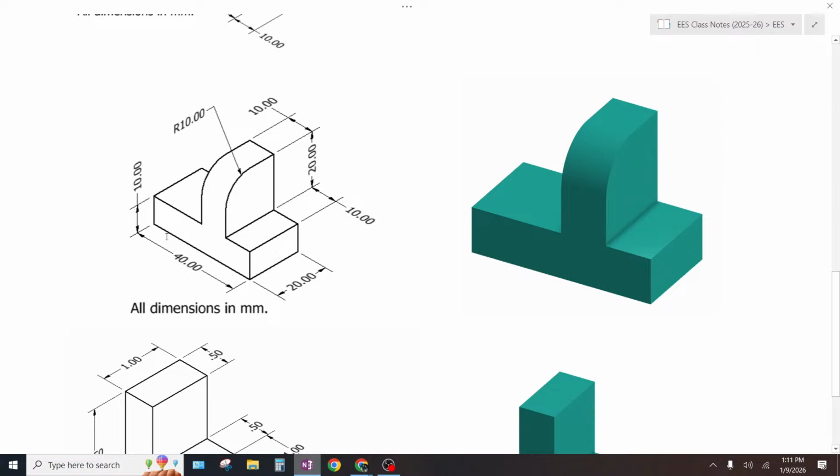You could draw on the front plane, this front surface, right? You could draw a rectangle. You could draw on the right plane and draw this rectangle, right? You could even draw on the bottom plane. It's called top, but you can think of it like drawing the bottom and draw out this overall rectangle and extrude up. You could do all of that, and then you'd add this top part later. Sure, definitely could do that. What else could you draw?